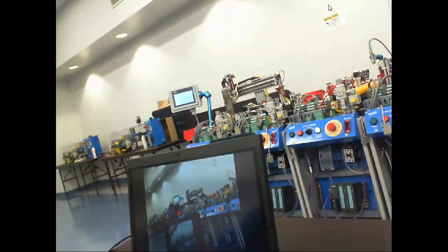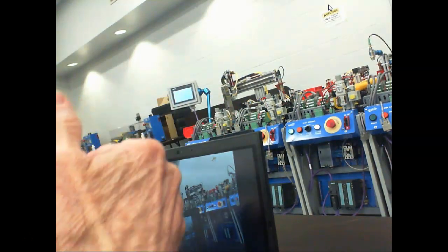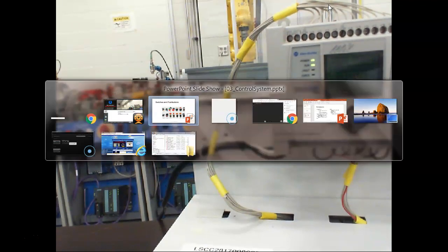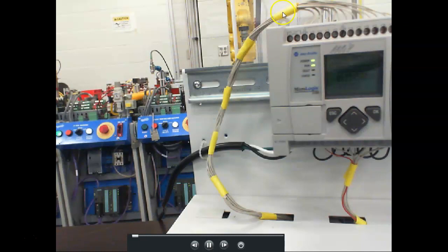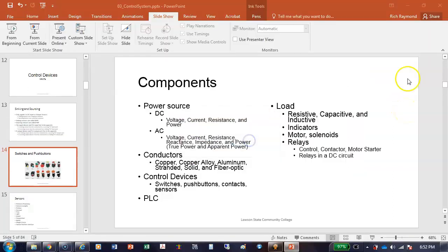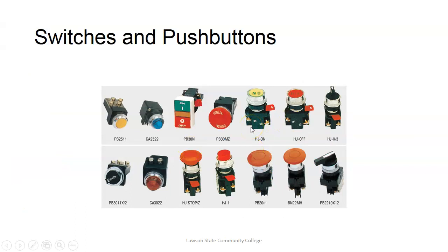But these guys right here actually use what we call resistive panels. So you literally push in on them and you actually change the resistance where you're touching. But you have to push on these. Anybody that's ever used these, you can't just touch them like you use your phone. You literally gotta push in on them. So these push buttons are usually big enough to be operated by people wearing gloves. We don't see any small things out there. We see large push buttons. So these are pretty common.